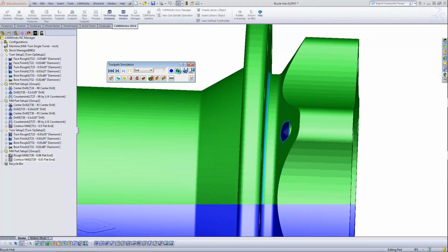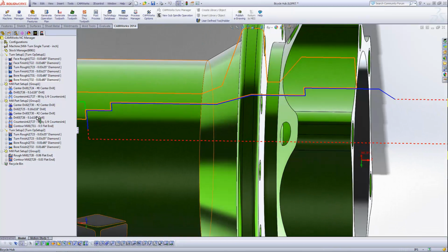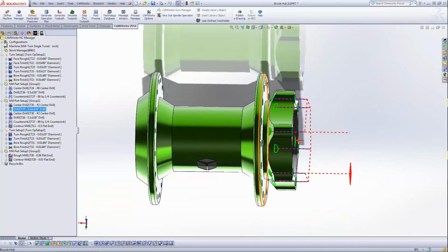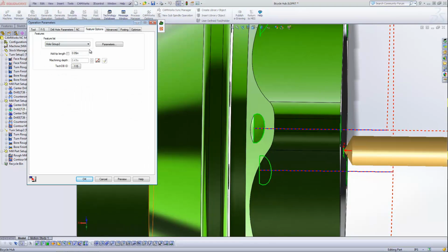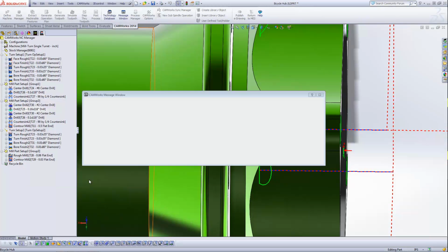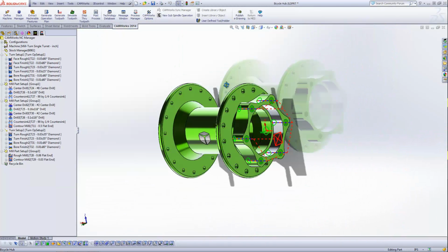No, I'm only undercut because of the radius on the turning insert and the fact that there's a sharp corner in the model. So that's a case where I just have to say, you know, I probably can't do that, and if they need it done, then we're going to have to figure out a different way to cut this. It looks like I am undercut on the hole, not quite deep enough on the hole, and that's an easy fix. So if we find that the drill operation on that hole, there's a setting to include the tip length. So that will stretch it a little bit deeper, and we'll be deep enough on that.